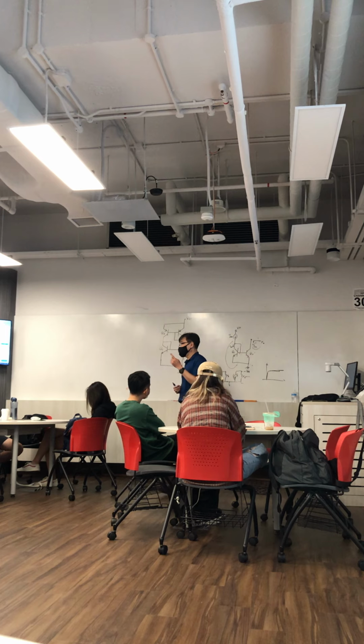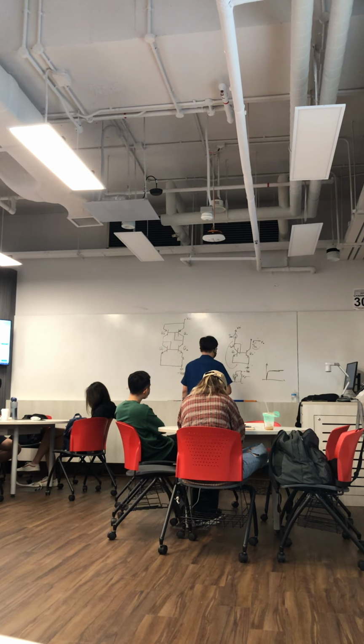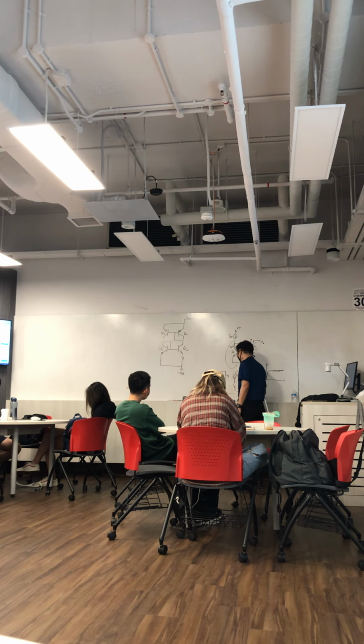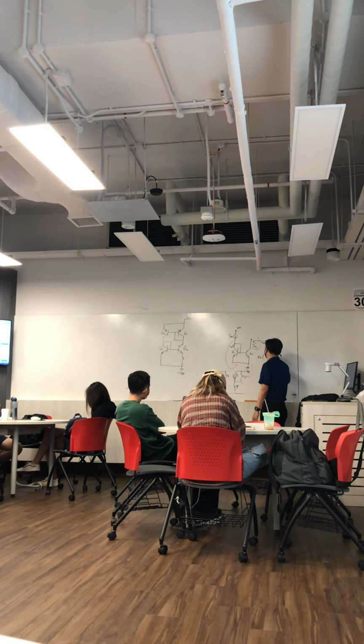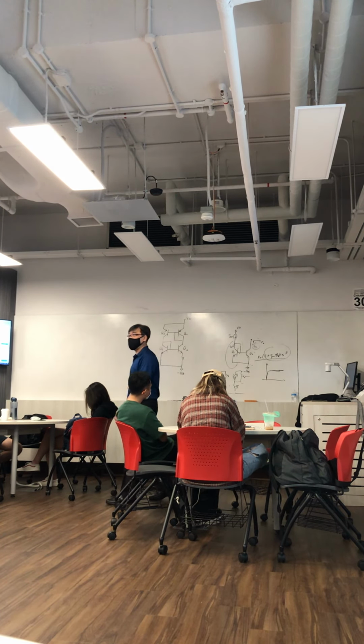Think about it. When you do your common emitter amplifier, there's one very useful case I showed you before. If I put an emitter resistor there, the output resistance will rise by 1 plus gm RE, something like that, right? Yes, precisely. If you put a resistor there, then you find that the resistance, you work it out, will be R out times 1 plus gm RE, approximately. But it could be this guy in parallel with r pi, something. So that means I raise it by this factor. Make it several times of R out.